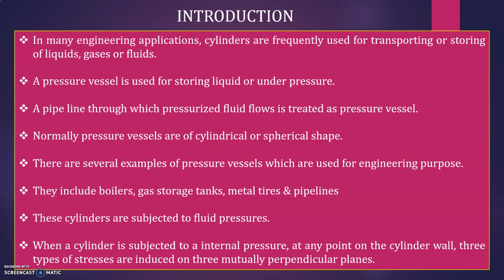When it is a gas, the pressure is constant in all parts of the vessel. In case of liquid, the pressure is lowest at the top and increases with depth. When the vessels are empty, as I already told, they are subjected to atmospheric pressure both internally and externally, and hence the resultant effect of atmospheric pressure is nil.